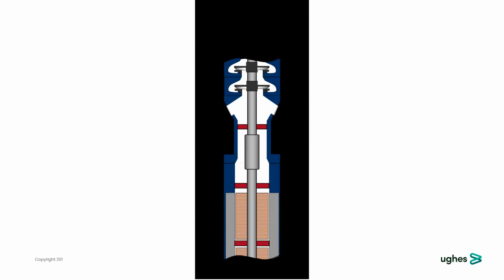So the first main function of the seal is isolation. This diagram you can see here explains what would happen if we coupled our equipment together and placed it into the well. That means the fluid from the pump would be connected directly to the motor because there is no isolation between the motor and pump.